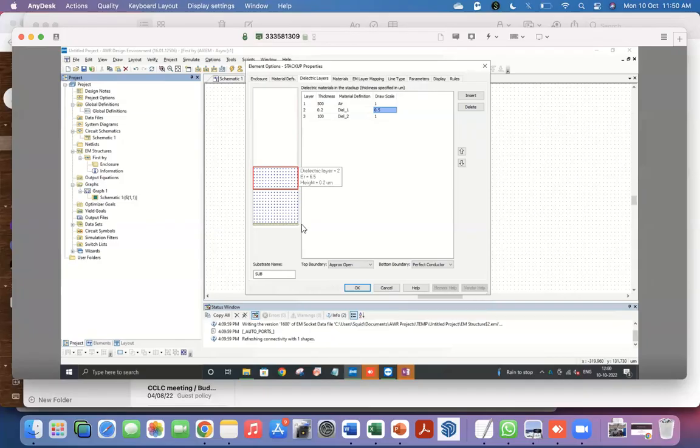Well, there is no cavity here. The enclosure of the whole system: first of all, nothing is defined on the sides. So it assumes that you're not going to be trying to simulate a system where you have side metallic walls, which might be the case in a general scenario where your whole thing is enclosed inside a box. But it's usually a bad idea for your transmission line traces to go very close to the edge so that they start interacting with the side walls. So it assumes that there is no side wall problem here.